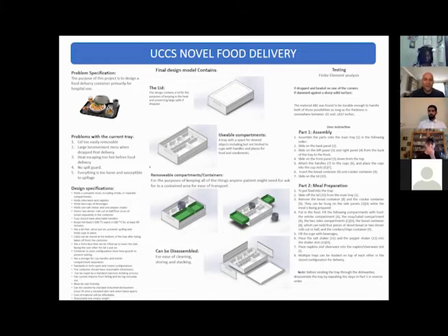Finally, the overall design of the tray met his desire for the lid to be able to be removed. It can slide underneath for easy storage, and the tray was able to withstand all of the FEA testing that we did, and withstood the drop test, the test for rigidity, the test for stackability, and all of the other tests, which means the product will stand up and be usable for many years to come.